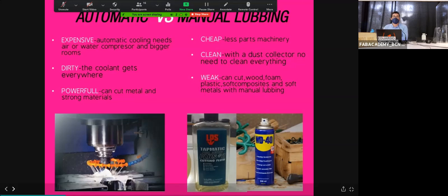It melts together, it bonds. That not only is really bad for the machine because it can lead to a motor breakage, etc., but there are ways to avoid that. First is on the settings. If you use the proper settings to cut the proper values, you can cut aluminum, for example, without cooling. You can cut steel without cooling at all, just using proper values. You have a really small margin to cut. If you get above that margin, you have a failure.